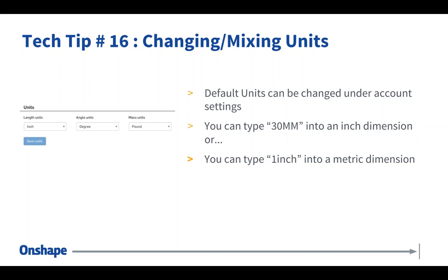Question: would love to share selected parts from a part studio. Any recommendations how to solve that right now? Yes, use the derived feature to insert the part into a separate document. It's not an ideal solution, but it allows you to share, insert the parts. They're linked to the original. You can insert the assembly and then share that as a separate entity.